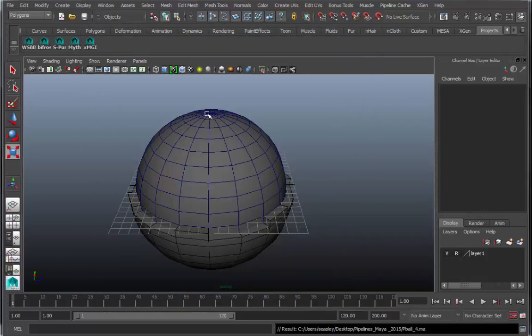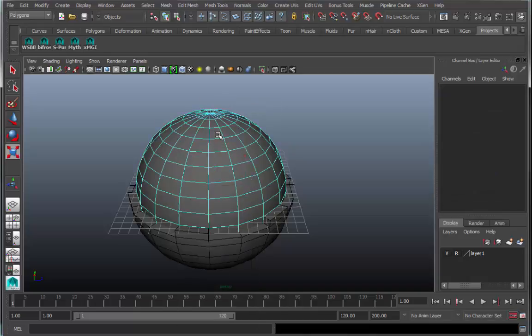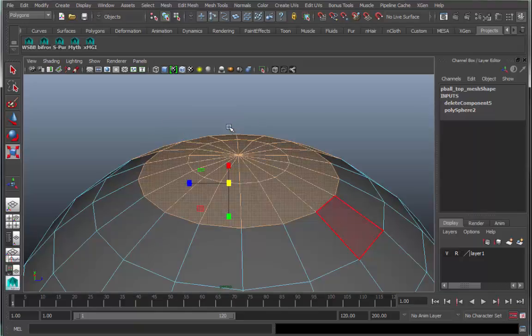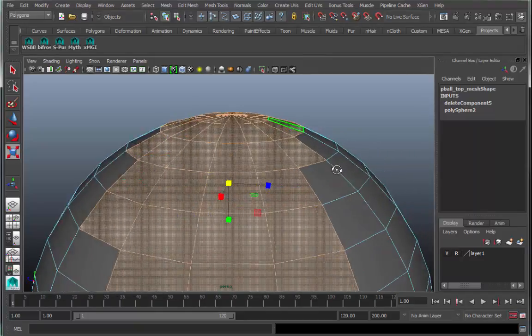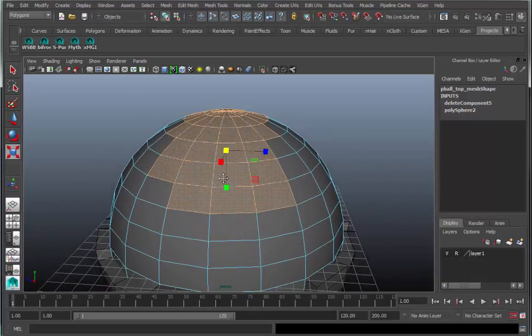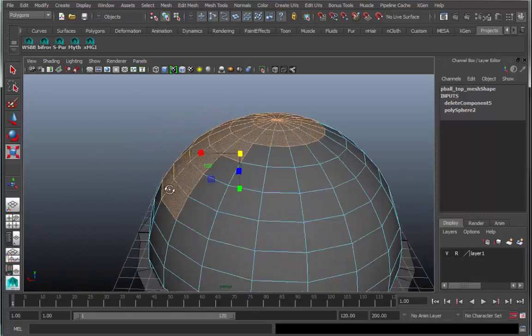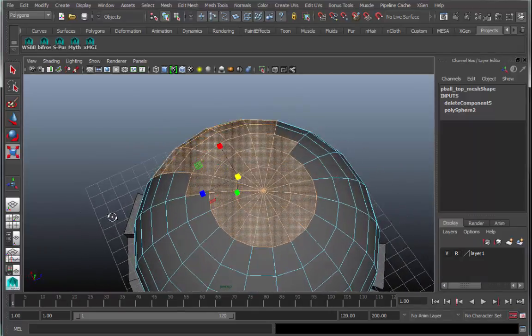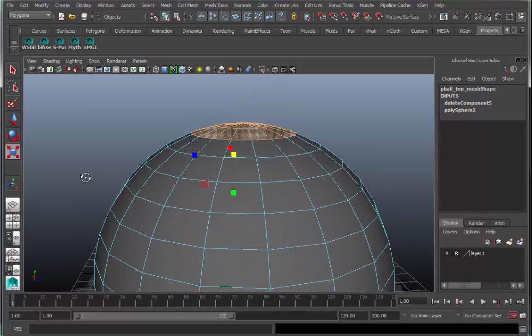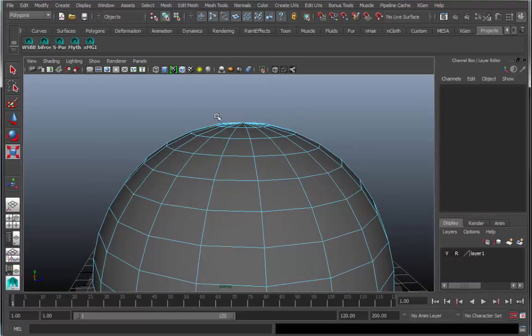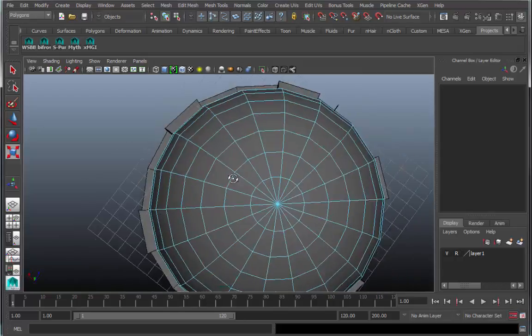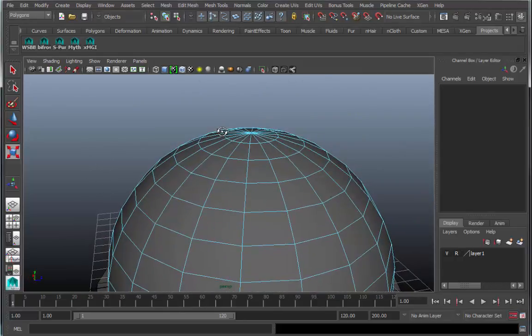Okay, to move on, let's go in and grab just this top ring of faces on the top of the Phantasm ball. What you don't want to do is this. Again, it's perspective, so it's going all the way through. Frankly, it's sloppy too. Look at the faces I've inadvertently selected in the back. And if I were to translate these or rotate these or God forbid extrude these, I'd have a huge mess on my hands. So we want to be able to use, and I see people doing this, they just kind of stay in perspective view a lot. Ultimately this will hurt you.